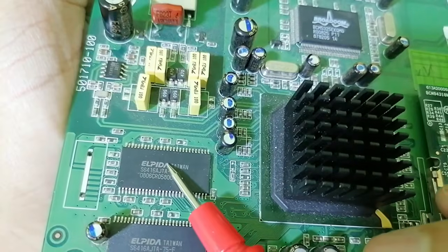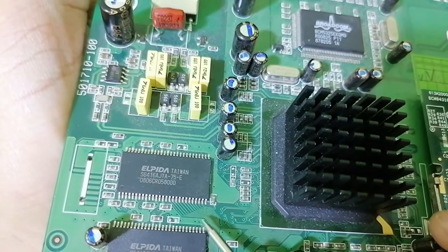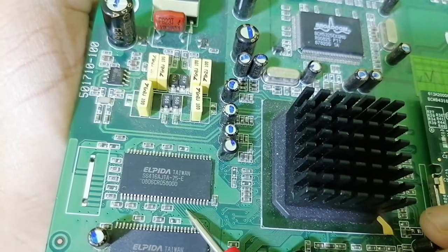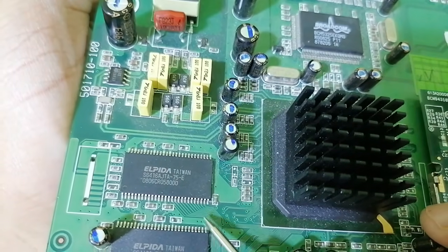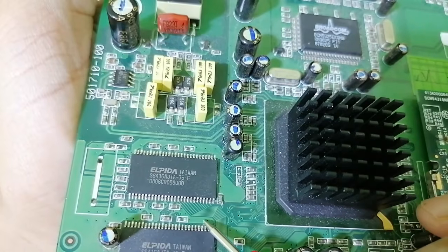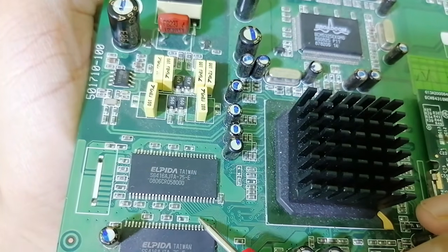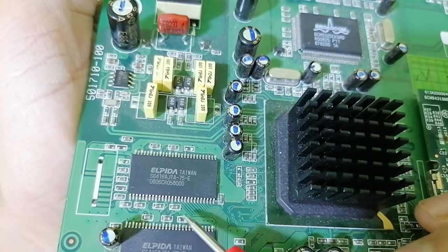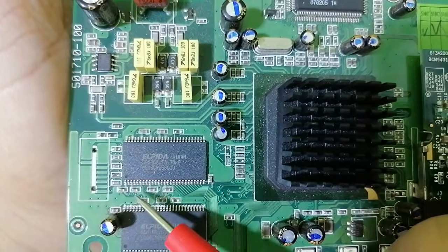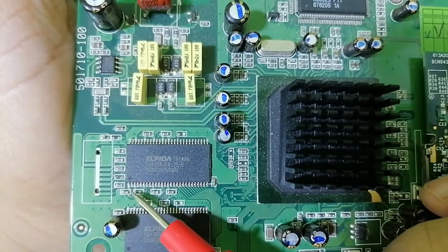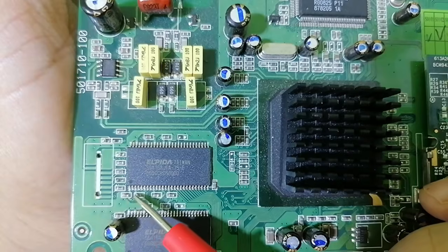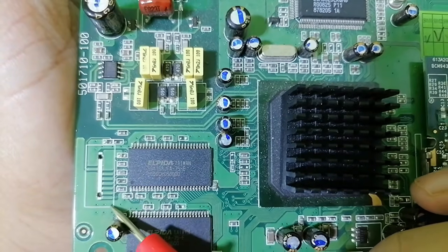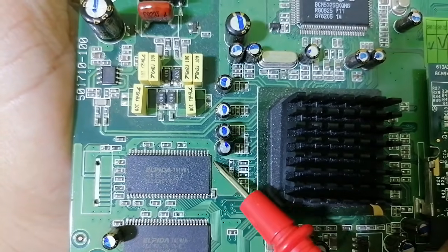So do you see for this IC, for example, here we have many lines and paths. This is basically for control signal. Do you see? Thin lines. And over here we have a very bolded line. This line, as you can see here, this is ground. This is not input voltage. This is ground, okay? And over here we have control signal. So here do you see this bolded line, and this is also connected to the ceramic capacitor. So this is the input power over here. And here, as you can see, this is the ground. Okay, do you see the ground?